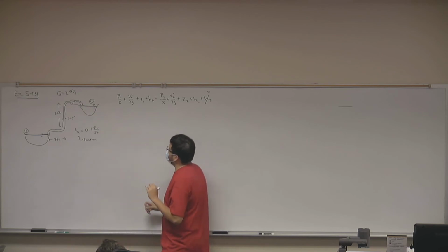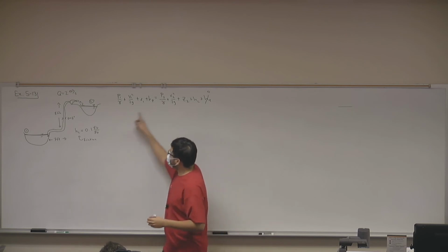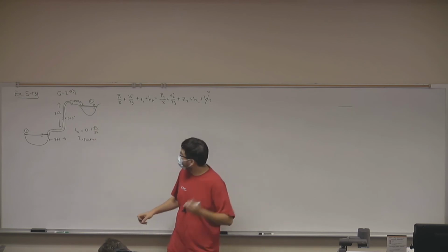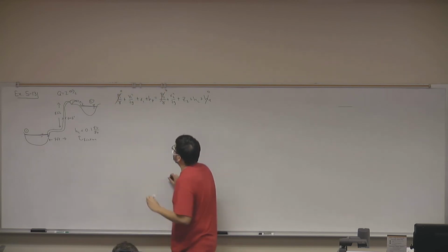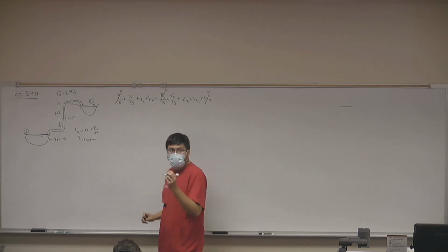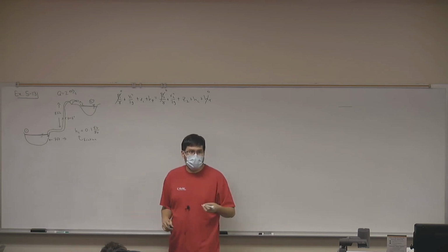Now why am I doing that? What's the pressure at the surface of water? Zero. Okay. What's the pressure at the surface of the other water? Okay. So atmospheric cancels out. Good. So if we were to start in the pipe, we have to know how deep the pipe was. That's correct. And then your pressure will be just gamma H.